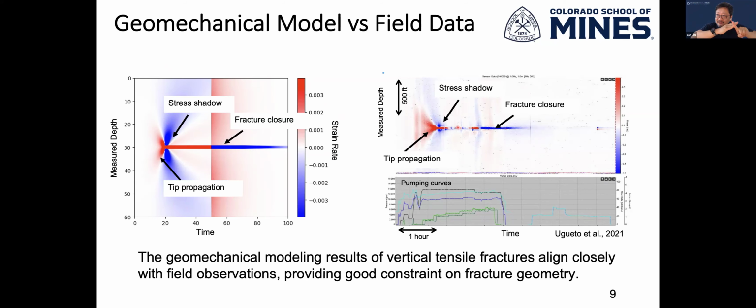Remember, my well is a horizontal well, so a parallel fracture means either a horizontal fracture or a vertical fracture, but parallel to the well, okay? And also it has to have a shear motion instead of tensile motion. So basically it needs to be a fracture that is not really opening up, or the majority of movement is not opening. The majority of movement is actually shearing and propagating. So it's almost like we're triggering some kind of fault or natural fracture and making it shear by itself.